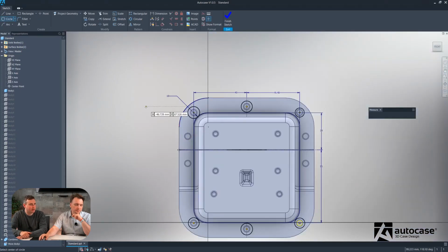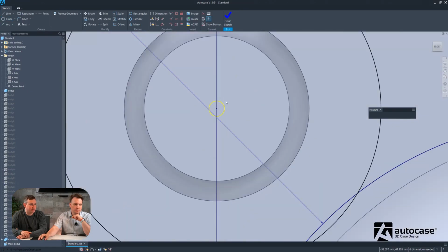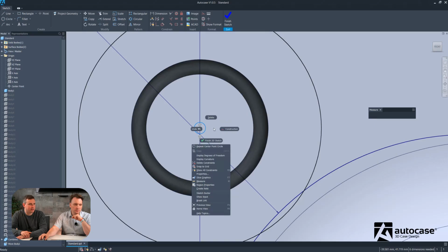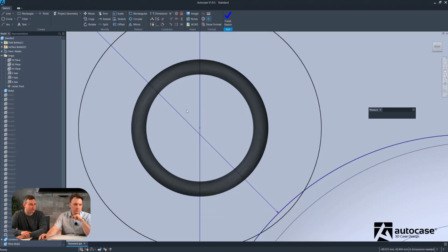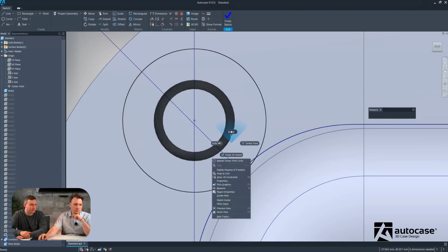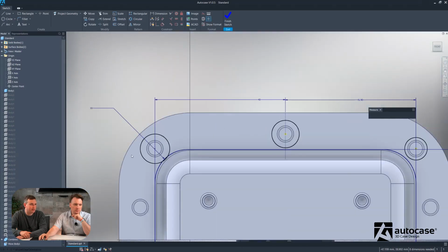So now we can go round, and probably before we go too much further, in the process of creating these circles, we've probably created some extra geometry in there we don't need, as you can see there. So by selecting over it and then deleting, and you can also do a slightly wider drag and click, in order to make sure that none of those inner circles, if you go slightly larger just to capture, that's it. You can just double check that there's nothing else in there.